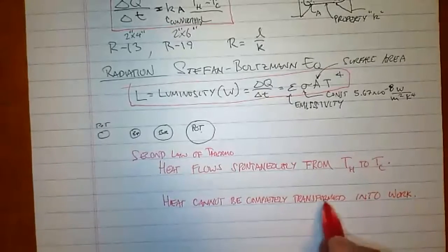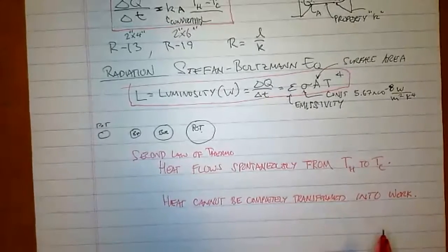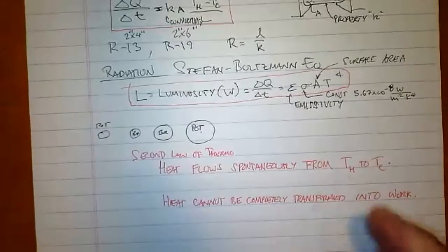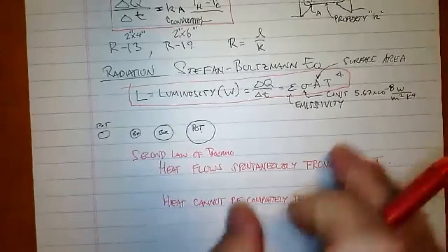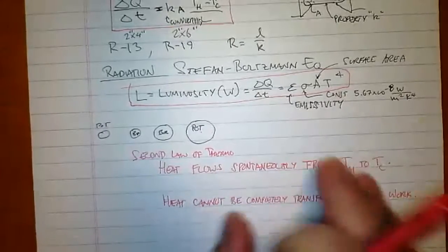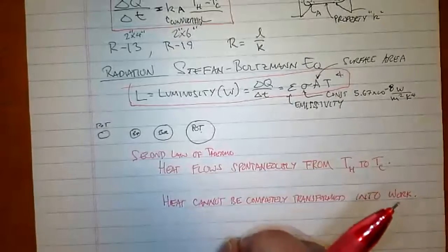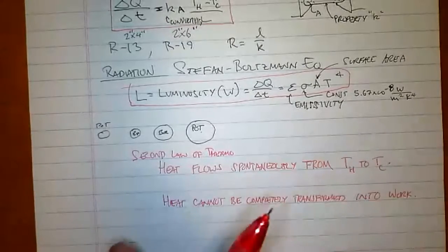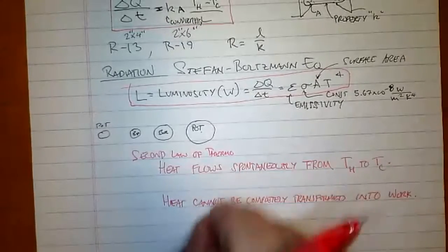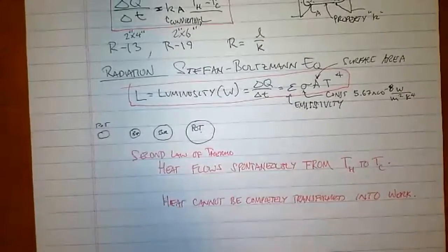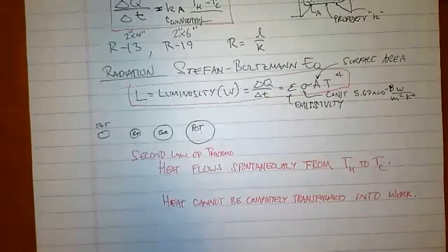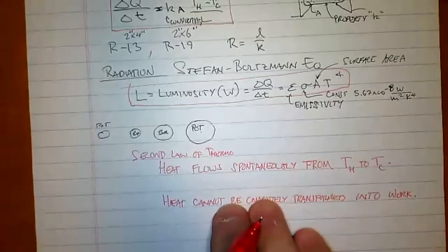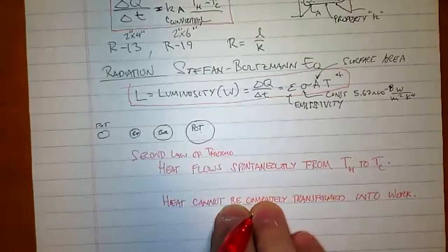What I like to think of this is heat is a low quality type of energy. What heat is, remember, is that internal energy. It's the average random kinetic energy of all the molecules and atoms in there. So once you've got a certain amount of that heat, how hard is it to pull exactly that much heat out of all those atoms and molecules? It's almost impossible. So you're pretty much just going to leave some fraction of it to be wasted.